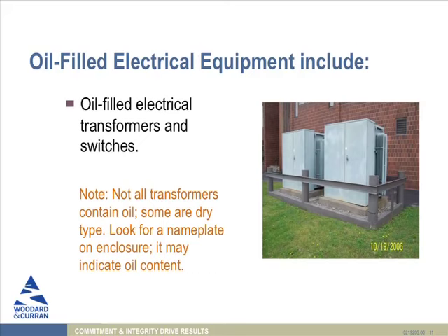Another point is that if the transformer is not owned by the campus, if it's owned by the local power company, technically it does not have to be covered under your plan. You don't have to count it as your capacity. It's not your piece of equipment that you're responsible for. The utilities should be managing that under their own SPCC rules.